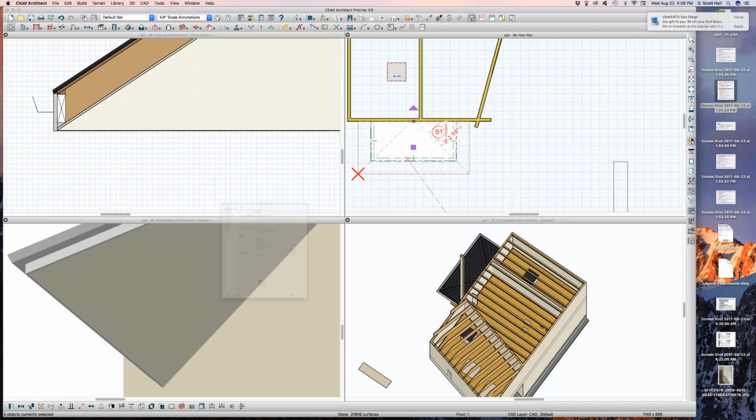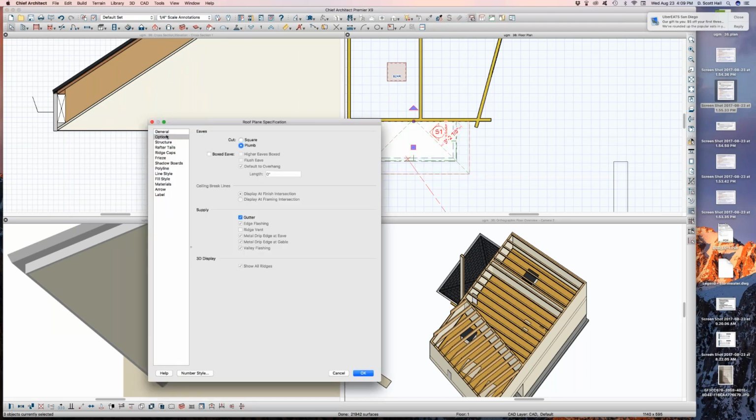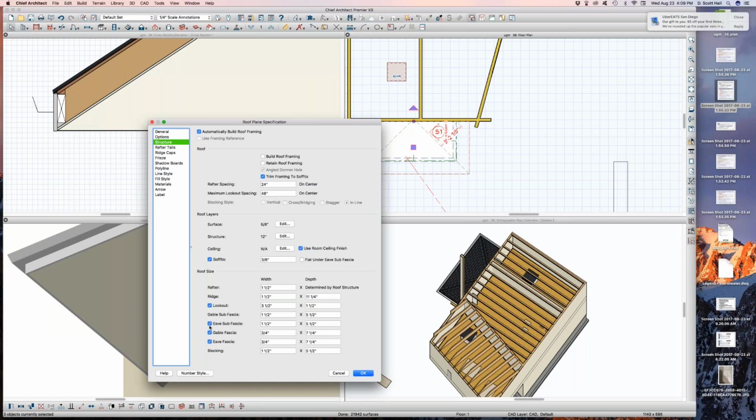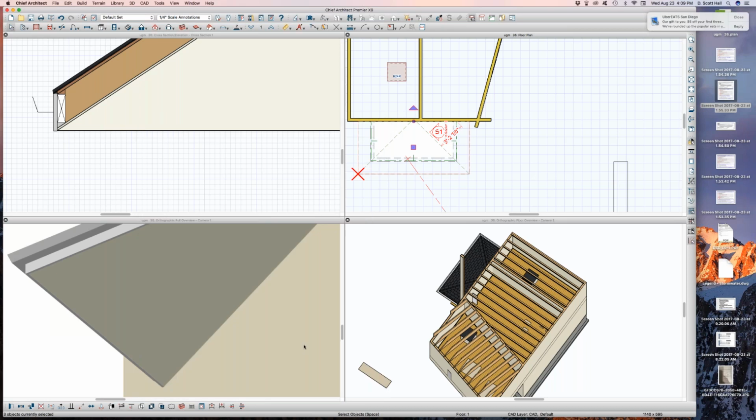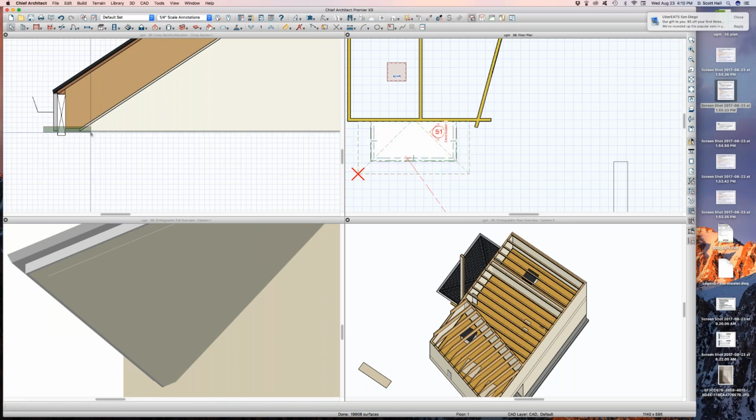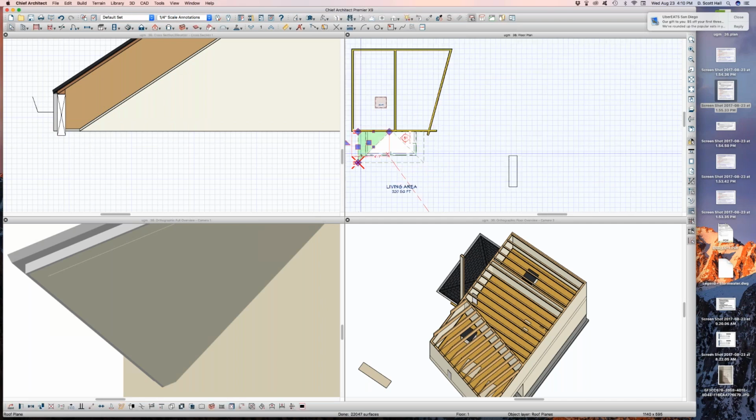Yeah. Here, I'm going to make those rafters thicker because I want to. So I'm going to come over here to the subfascia and make it 8 and 8. What's the difference from just adding drywall to the bottom of the rafters? Good question. And now it's just trimmed to the fascia. This slope right here is determined by the subfascia. That's what's going on. But Chop, if you remember at the very beginning when I did this, it was a mess. I had to change it to a box deep, and then I did it.